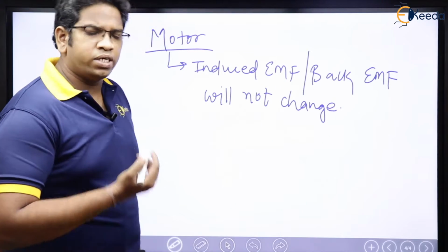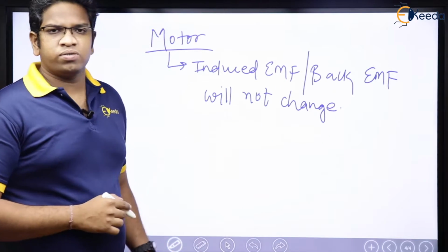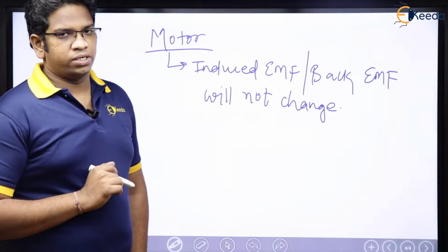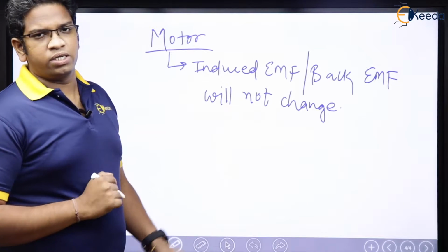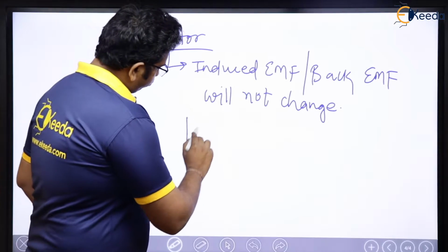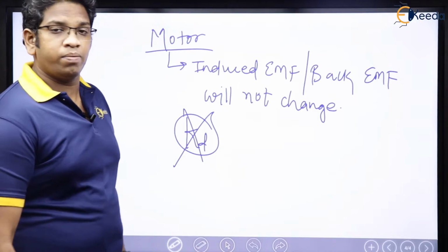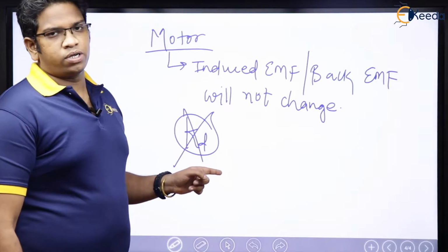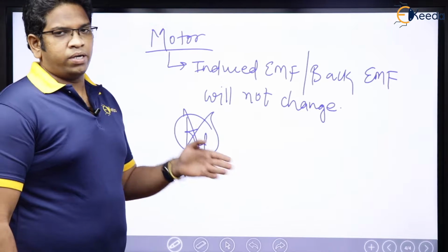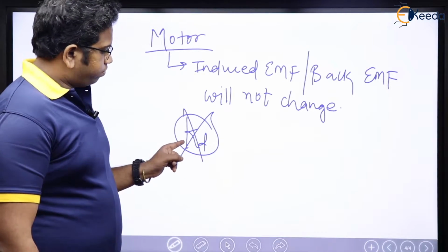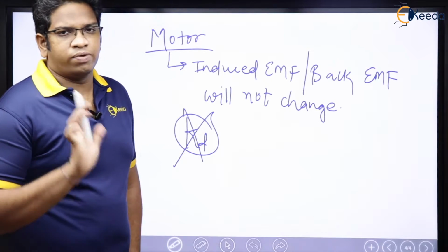Then what will change, sir? Induced voltage is not at all changing, right? Then what is going to change? Let us see. If induced voltage is not changing, then you may say, sir, there is no need to think of KD. We will simply ignore it. You cannot ignore. Why? Because the stator of a synchronous motor is the same as a generator only, right?